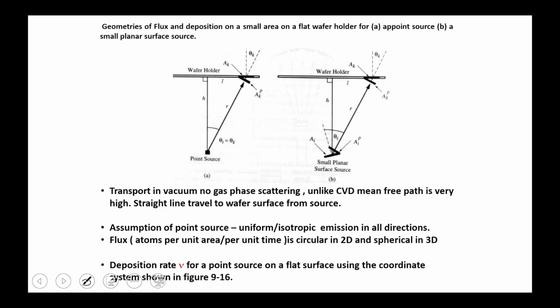So this is the vapor holder, and the angle between the substrate determines how the atoms will strike on the sample holder. If you hold it at some angle, the point source will move with some angle, and that affects the condensation of atoms on the surface. So the topology or morphology of the devices you can change through the angle or holding of the substrate holder.